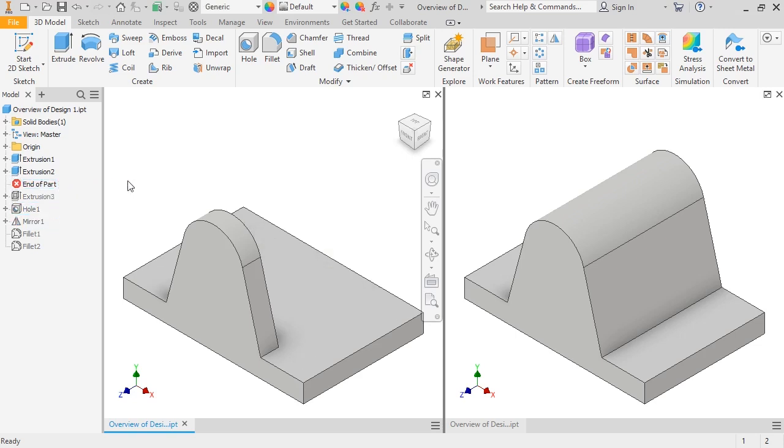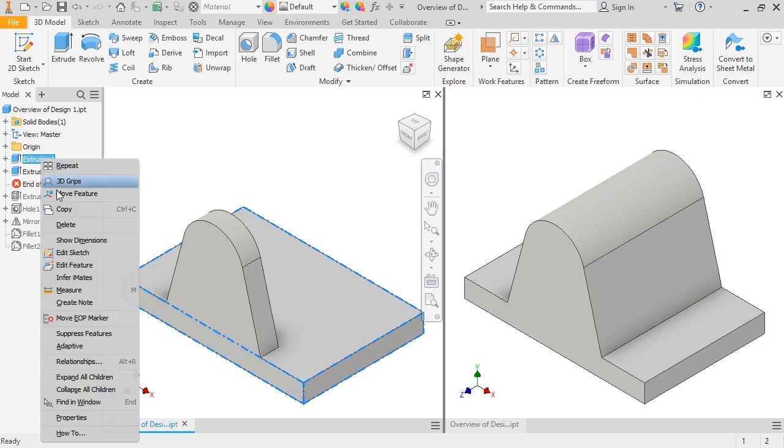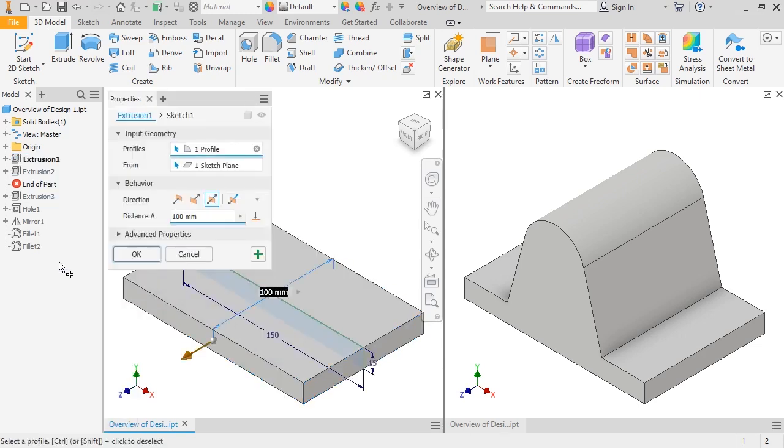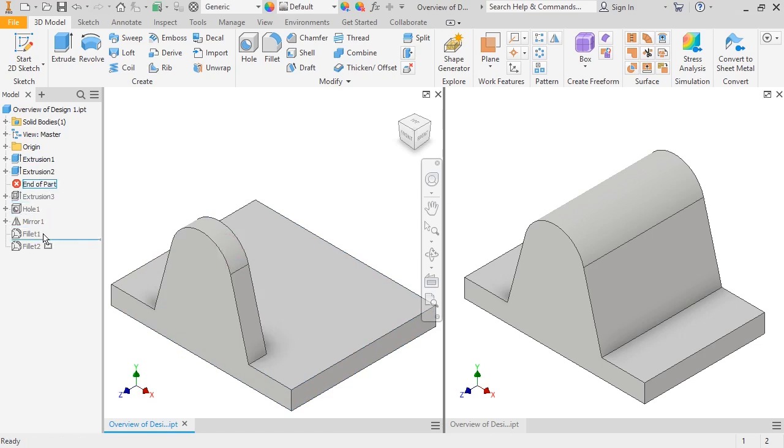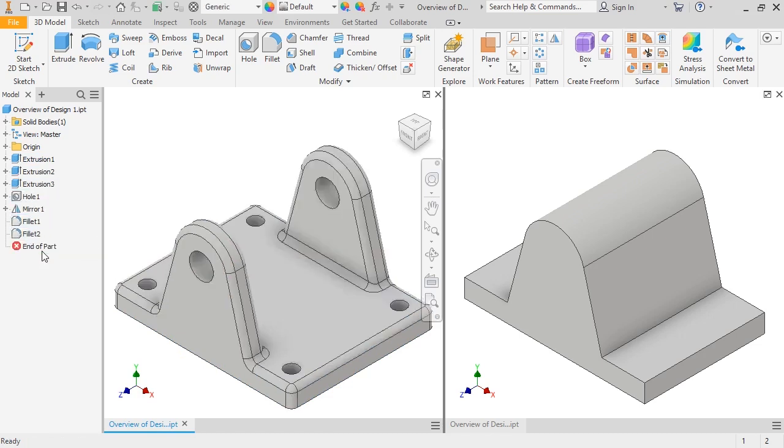When considering design intent, it's important to weigh the pros and cons of a design path, especially if you're torn on which way to take. One of the most common considerations, then, is how can the design be edited? If, for example, I were to change the width on the base of both parts to 120 millimeters, what would that impact? I'll start with the mirror feature design, and when I increase the distance of extrusion 1, you can see that everything stays symmetric.